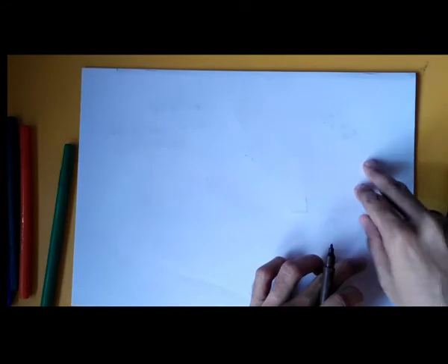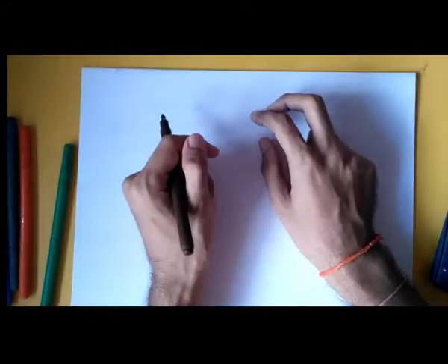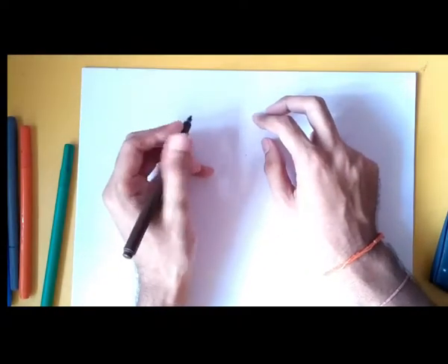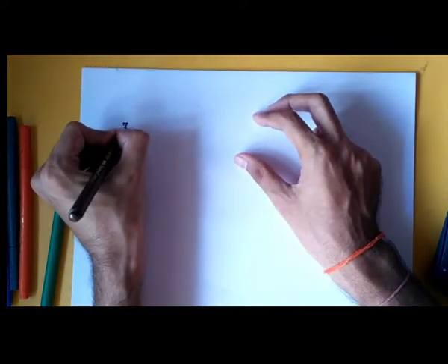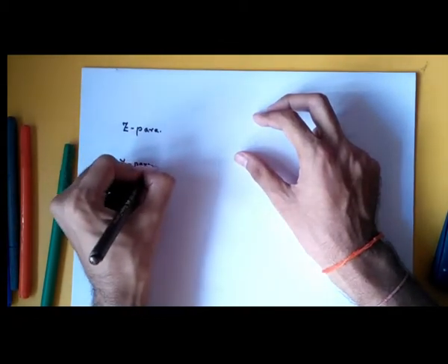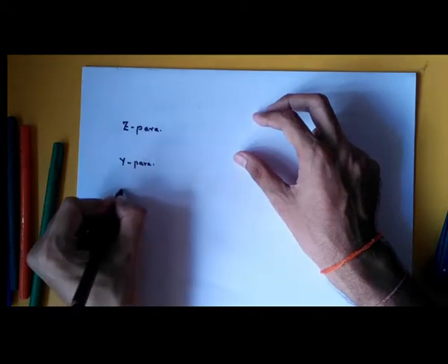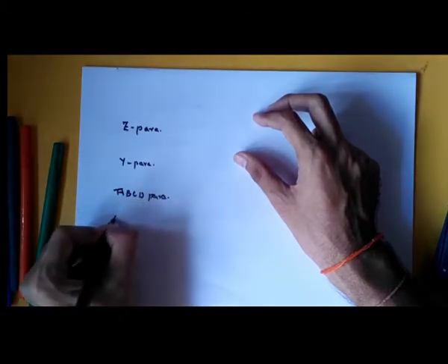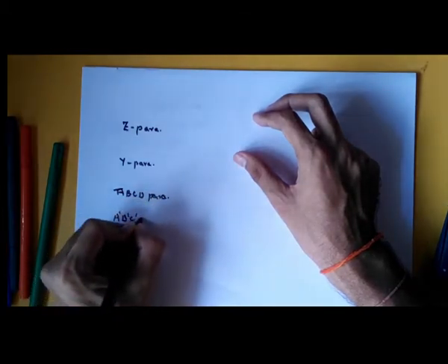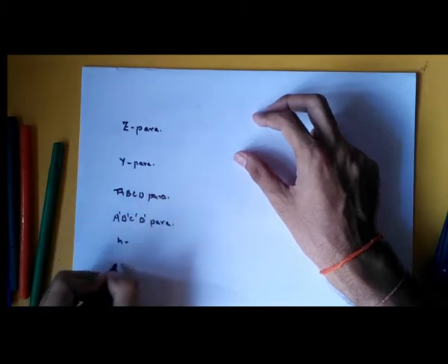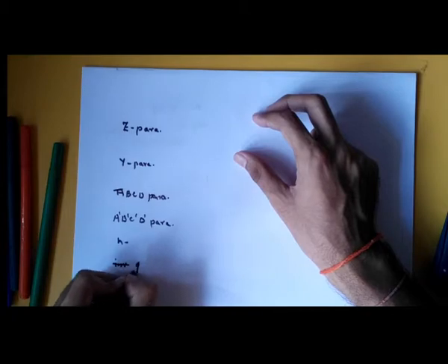So last lecture we started with module number 5 of the course Network Theory, which is two-port networks. Essentially, it is the two-port parameters which we study. So what are those parameters? First we saw Z parameters, then Y parameters. We just defined them. Then we had ABCD parameters, A prime, B prime, C prime, D prime parameters, then hybrid parameters and inverse hybrid parameters.